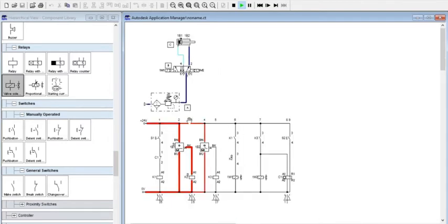Next we look at the electrical diagram. We can see the electrical flow from the 24 volt power supply through inlet port 1 to outlet port 2 and straight to the magnetic proximity switch at 1B1. Inside proximity switch 1B1 there is a normally closed contact.